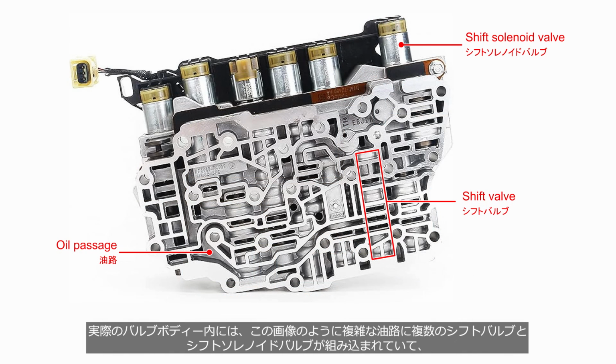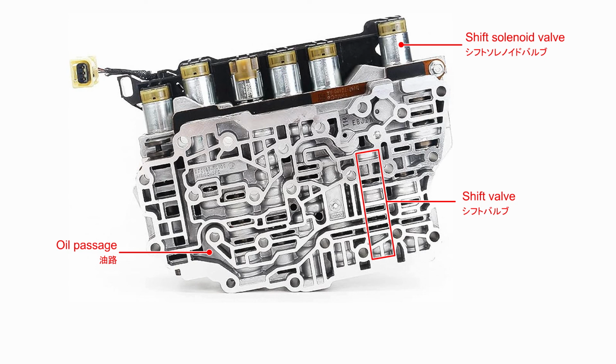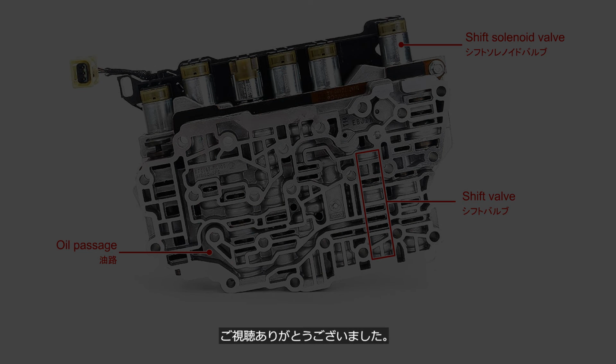In the actual valve body, as shown in this image, multiple shift valves and shift solenoid valves are incorporated into complex oil passages. In automatic transmissions, shift changes are achieved by combining the on and off states of these shift solenoid valves.